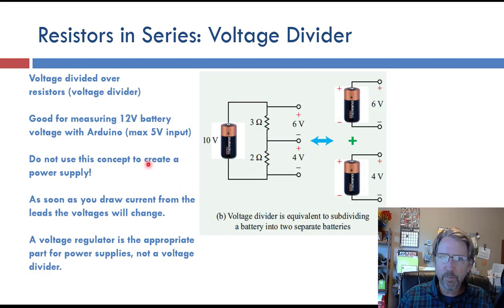It is really good for sensors. If you have a sensor that sends a voltage that's too high to measure with your data acquisition system, a voltage divider will reduce that, but still keep it proportional. So if the voltage changes on your sensor, the input voltage changes.